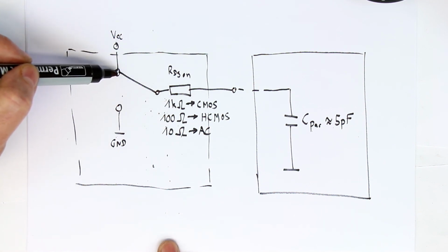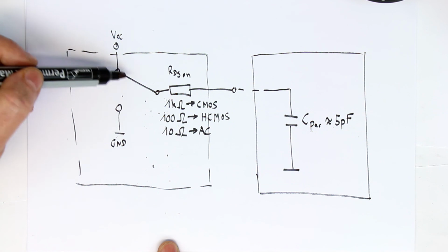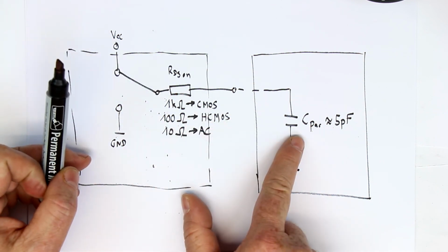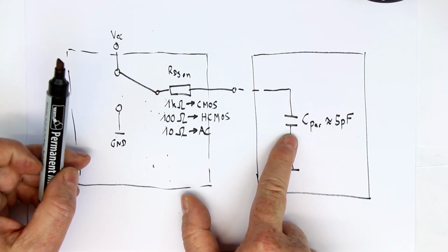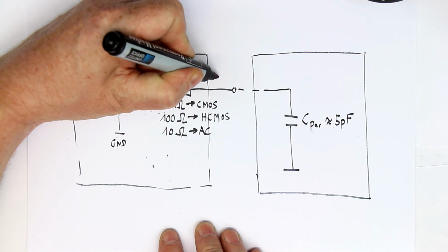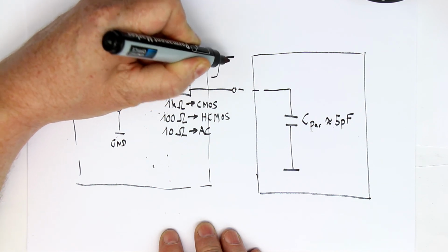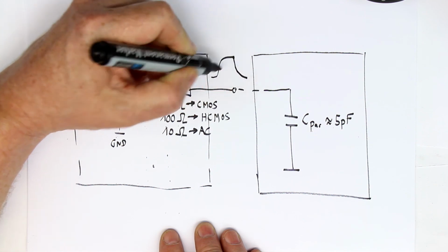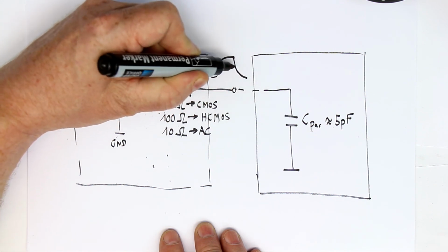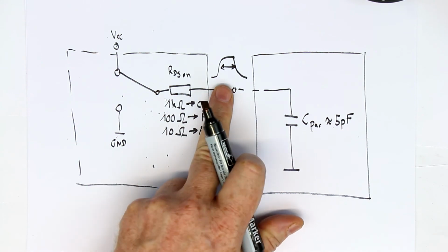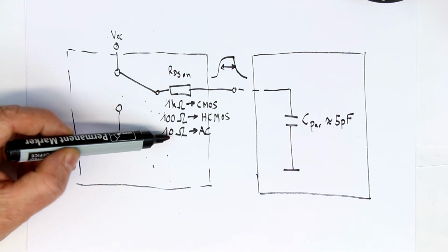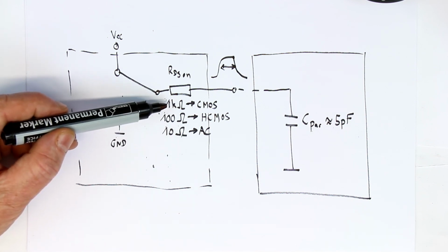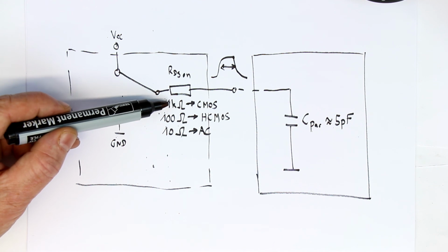When the output switches from VCC to ground or the other way around, first of all, the capacitor has to be charged, and it has to be charged so quickly that we don't have a slow rise time, and between charging and discharging the time must be as short as possible to reach the highest speeds. And you know, this sequence here is also a sequence of speed. CMOS, depending on which kind of logic gates you buy and from which company.